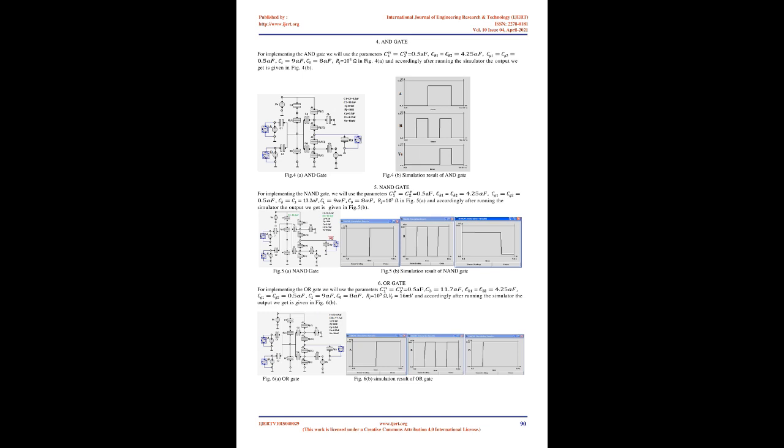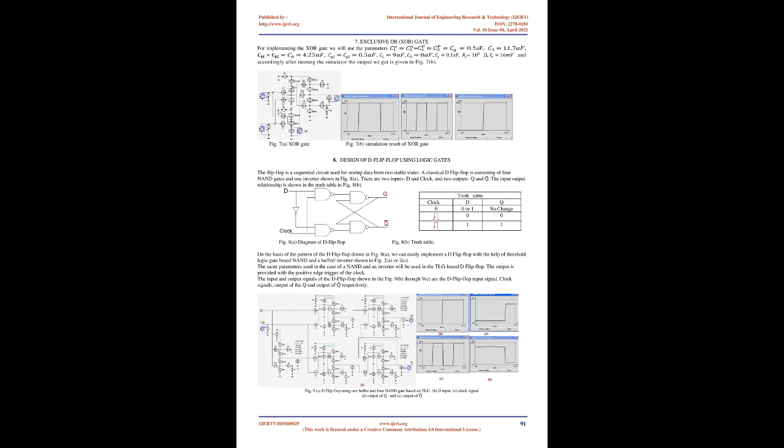Coulomb blockade interferes with the steady flow of current because whenever the high voltage, logic 1, is applied to the input, it causes a shift of the induced charge on each of the islands of the two SETs by a fraction of an electron charge and keeps SET 1 in Coulomb blockade and SET 2 in conducting mode. As a result, the output shifts from high to low.